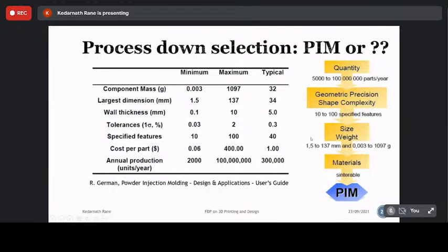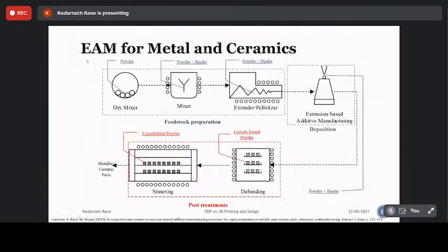We have the solution here, which is extrusion-based additive manufacturing. This process enables mass customization through enabling technologies, which are again PIM and MIM. We can use some process steps and add a step called deposition or 3D printing to enable mass customization as well as shape scalability.